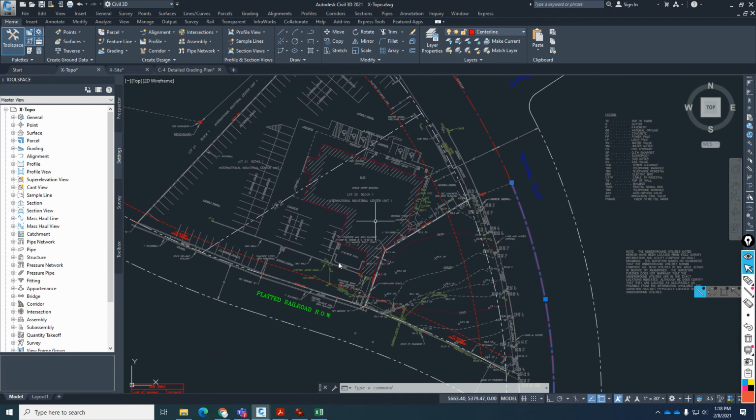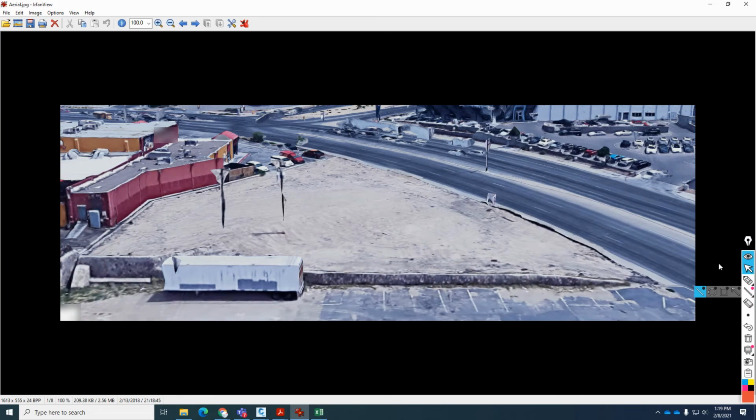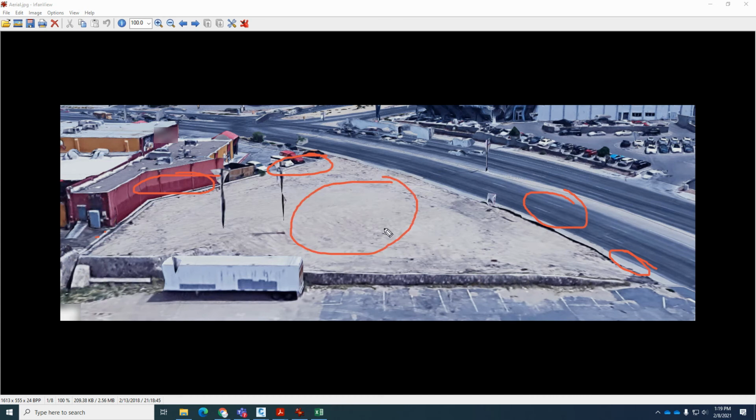When they survey, they also get some information that's adjacent to us, next to us, because we need to know that. When we're designing our building, we need to see: is there anything we need to worry about? Is there something we need to consider next to us? Is that building close, and how close is it? What are the elevations of the pavement on the other side? Is it a parking area? Is there a sidewalk I need to worry about? What about the existing roadway? I need to know all of these things so that I can better develop my site to make sure I have the right access, the right driveways, and all that stuff.